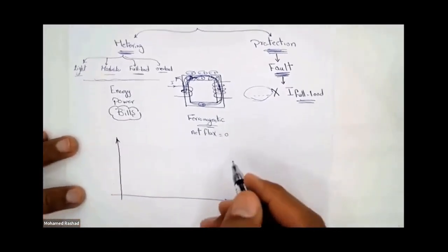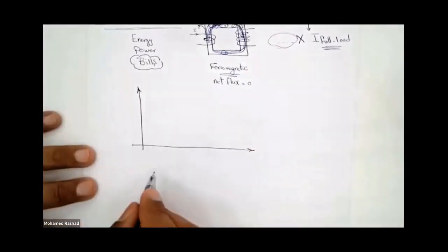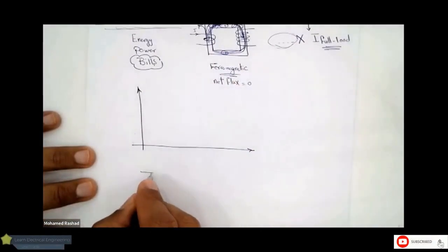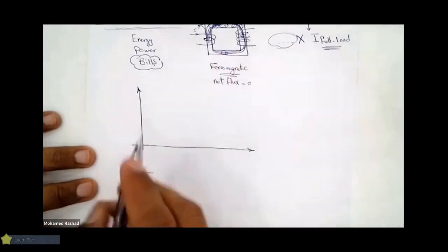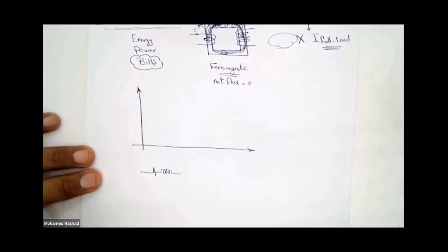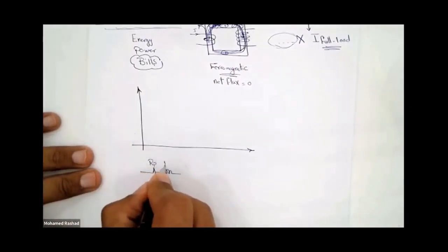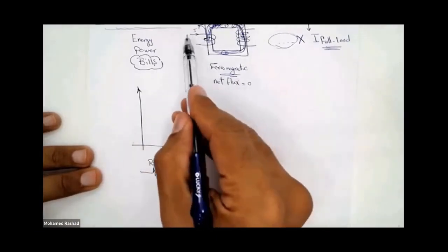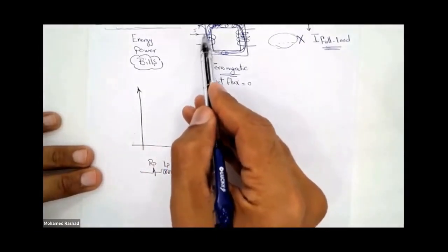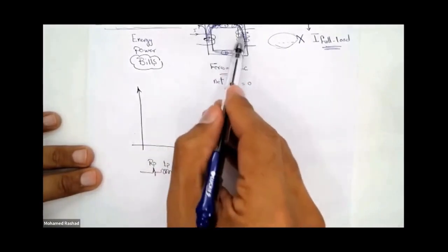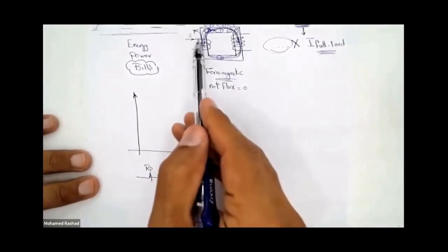So what does this magnetization curve tell you? It tells you that your CT, which you have drawn, consists of a primary. If I want to represent an equivalent circuit for my current transformer, it consists of a resistance and a reactance, which we call R primary and L primary. And the core itself starts with your current, which creates a magnetic field. The magnetic field begins to transfer from the primary to the secondary through an iron core, right? Am I wrong? Very good.